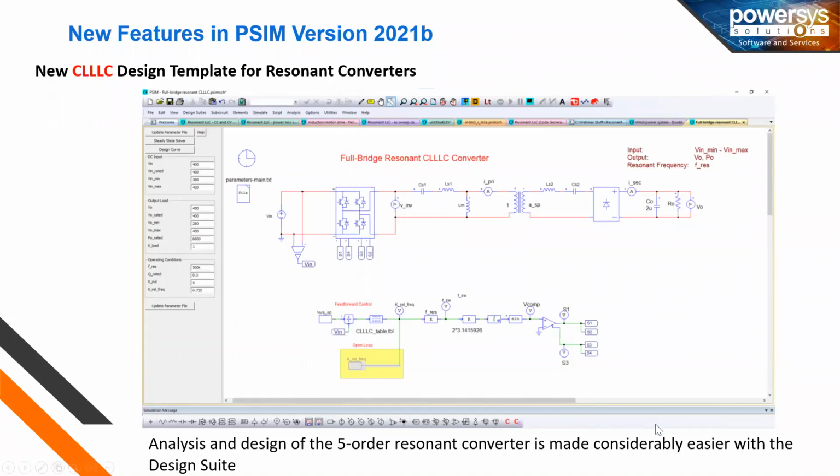You can directly modify the input and output voltage and the power, and check the different parameters like the quality factor and the inductance ratio against LM and LS, the magnetising inductance and this LS value, and directly the sampling frequency between the resonant frequency and the switching frequency as well.